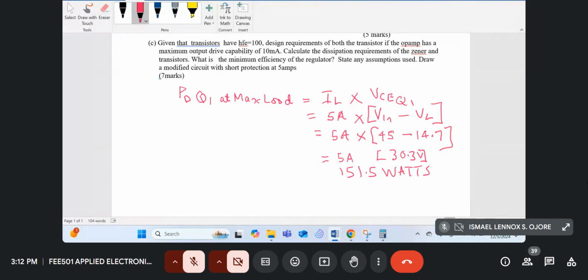In fact, that's the most common transistor that is used in the lab power supplies. It was rated at 115 watts at 25 degrees centigrade. So if you go to the shop and put that transistor inside this circuit, it's going to burn. Okay.